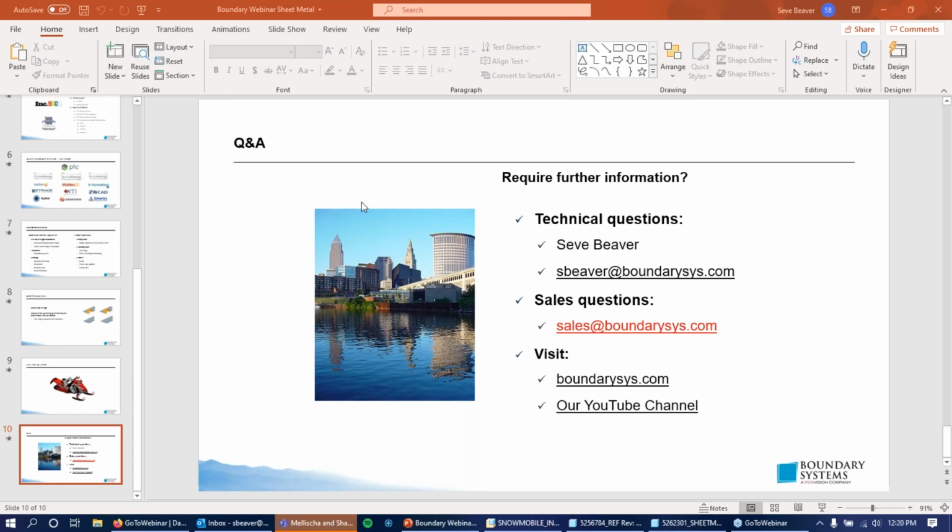All right, so first question is regarding the extruded cut feature. The question was, is it specific to Creo 7? So the answer is yes, I believe it's new to Creo 7. It may be new to Creo 6, but you are correct that they did change the name and the appearance of that extruded cut. It works, as far as I'm aware, exactly the same as the previous feature, extrude or remove material, what it was called before. But yes, that is actually new, and that's something I've taken note of.